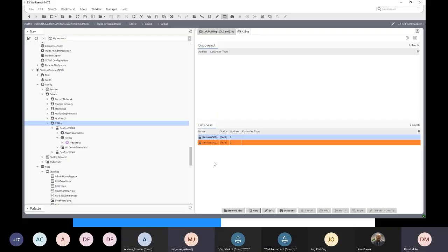Okay. So if you do that, it should come online and work. And now you need to change the connection as well, because the 3-pin plug on the NAE is different to the 3-pin plug on the FX80. The plus and the minus are swapped over, I think.